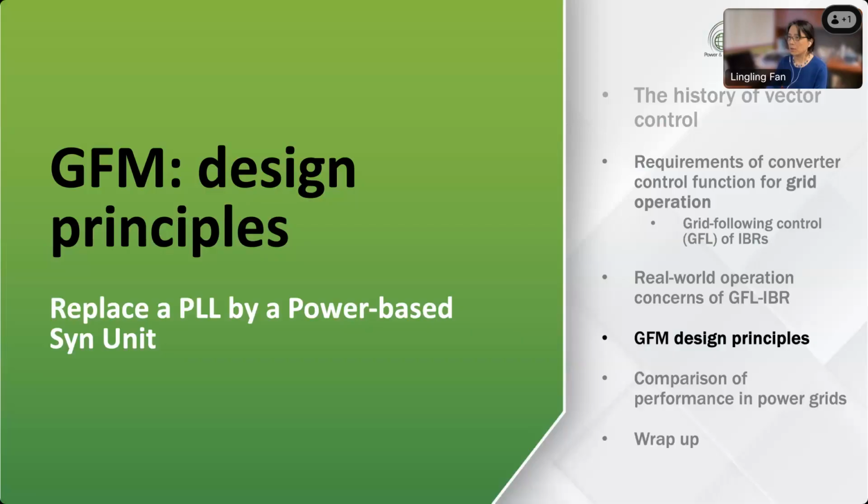So let's now move to the main topic of today, the GFM design, grid forming design. In the literature, if you replace a PLL by a power-based synchronizing unit, then people just call those GFM. So let's evaluate a couple of design principles. The philosophy is that the GFL design has been there for decades and works very robustly.